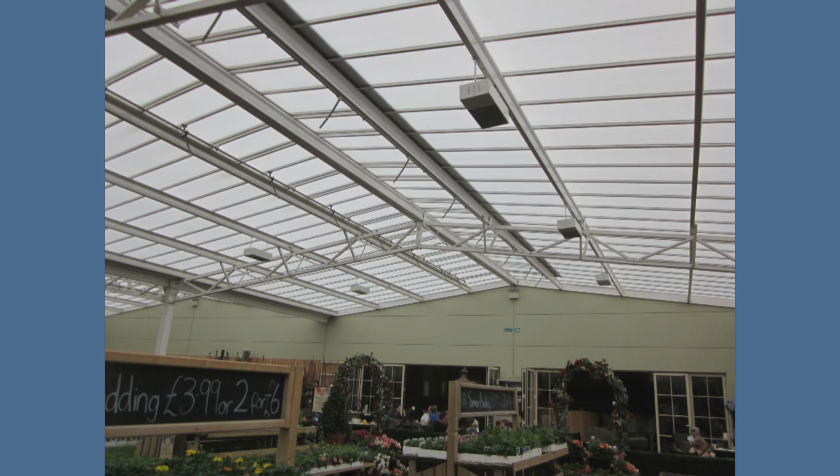This is another one. This is a very light truss, but if you look in the centre here, again, you've got a connection. In this case, 4 bolts again. This is a worrying one. The reason being that the plates here don't line up. Now, steelwork is made to a very tight tolerance, normally about 2 millimetres. So something has gone wrong there.